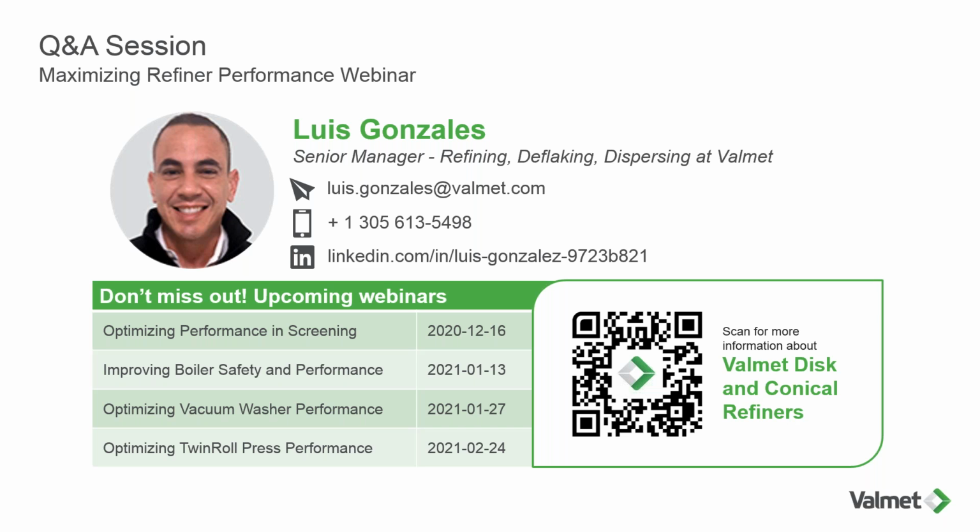As long as you have enough bar to get the pulp to the next chest, there is no issue with continuing to refine. So the answer is close to 0% bar height left if you can pump. Again, it's going to be very dependent on how far your next chest is and how much pulp you're going through there. If you're at the higher end of the pumping curve on the refiner, you're going to have to change plates with the bar still pretty high, because as you start wearing into these, there's not going to be a lot of pumping capacity left.